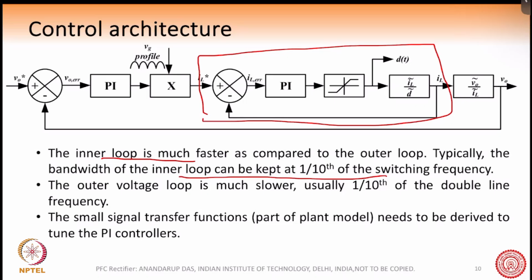So we have a minus 20 dB decay, a single pole behavior of this plant transfer function or the loop gain. And there we will see that at the switching frequency, the gain is falling. I mean, after the zero crossover, it falls at minus 20 dB per decade. And so for this inner loop, the gain should be very small at the switching frequency.